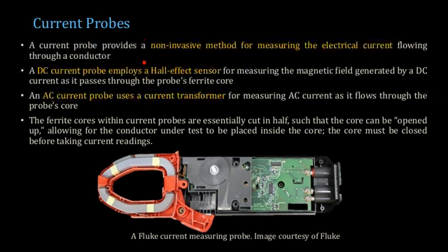The last type of probe that we are discussing is the current probe. So this is a non-invasive method for measuring electrical current. Here you can see that here is a gap available, and you have a core provided, and this is one structure, this is a second structure. These two structures are brought together using springs, and this can be expanded. This knob can be adjusted to operate this or expand this spring outwards, just like scissors.